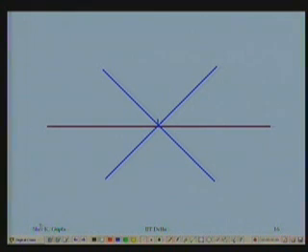Here I show you, this is a central dislocation and there is a region in the crystal around it. I talked about dislocations of the same sign lying on the same slip plane; here, they repel. But dislocations of opposite sign attract, which I show, let us say, by blue. These will be attracted. This is what we have talked about, right?